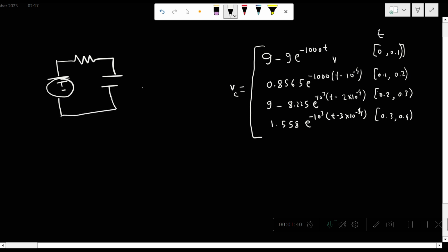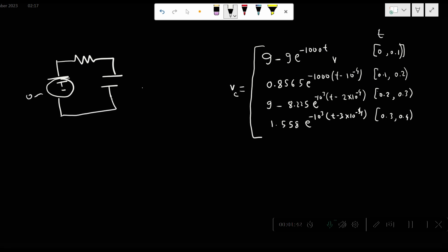So this is the pulse input, 0 to 9 volts, a 1K resistor, and a capacitor of 1 microfarad. Now, this is the equation I have written here. For this, you can refer to part 5 of the RC circuit series lecture. I have taken it from there. This is the first charging, then the very first discharging, then the next charging, followed by the next discharging of the capacitor.